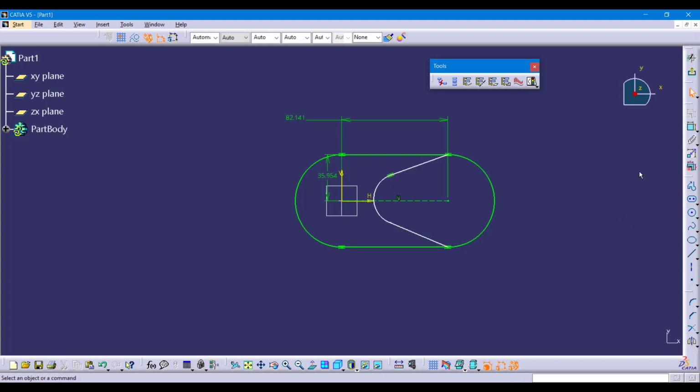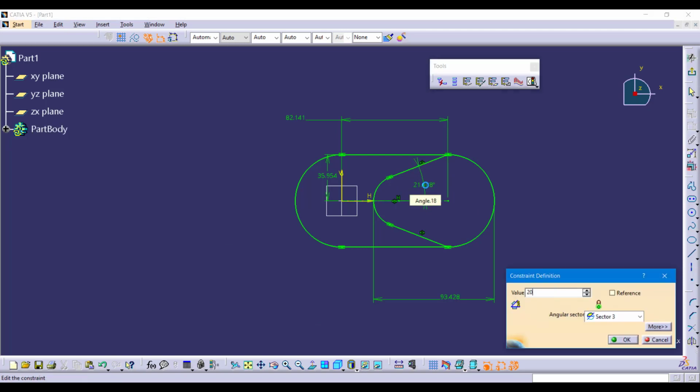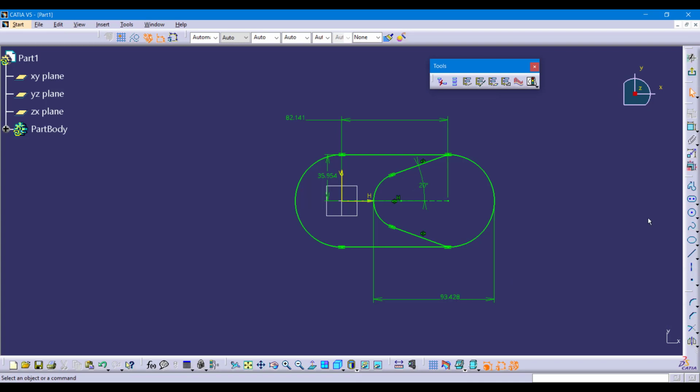Again, I do need to make sure that I fully constrain my sketch, so I will add a tangency on the bottom. Then I will apply a symmetry constraint between my 2 angled lines and this horizontal reference. I will give this a total horizontal length, and finally specify the angle of the line to the horizontal reference. Next, I will create one additional shape that I'm going to use to create basically a through hole, so making one more circle at the center point of that right arc.